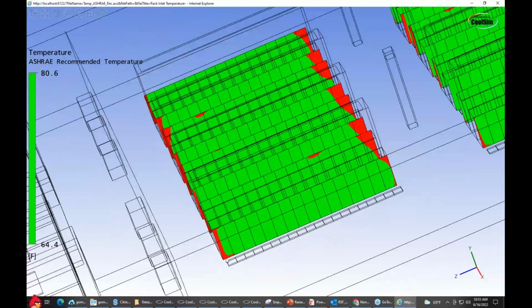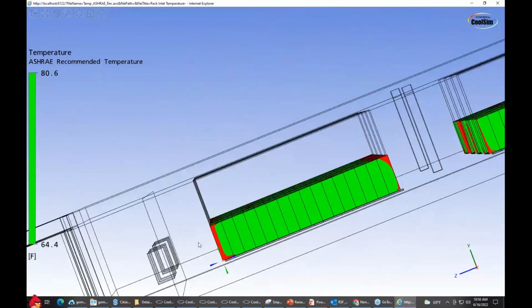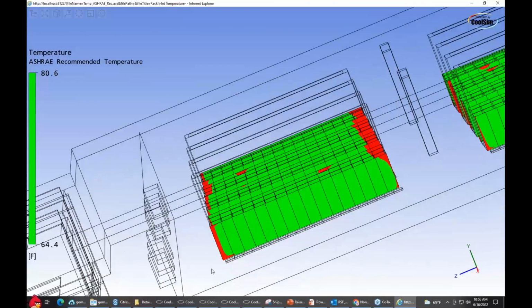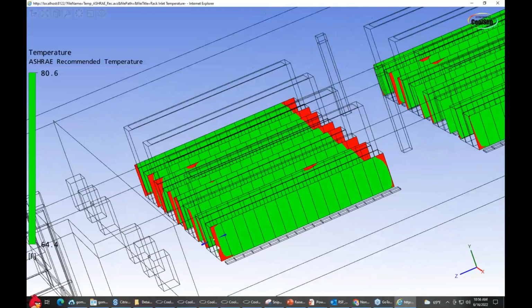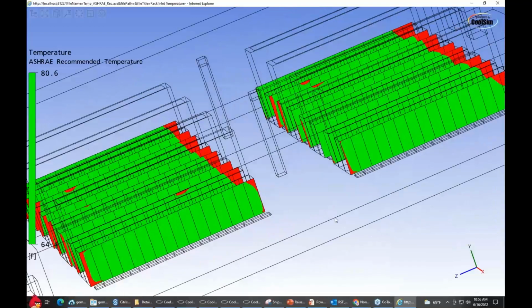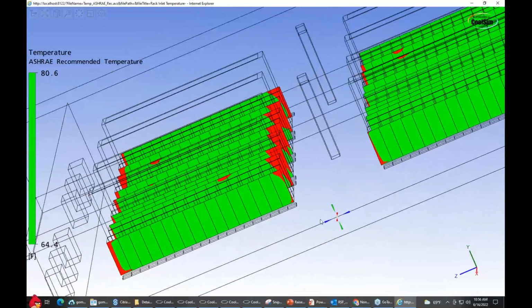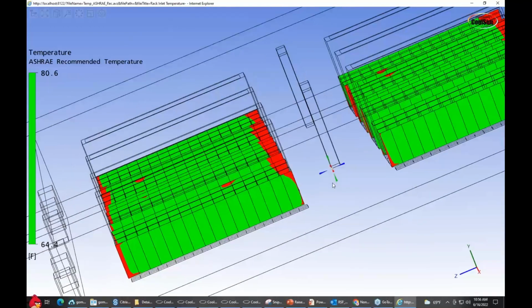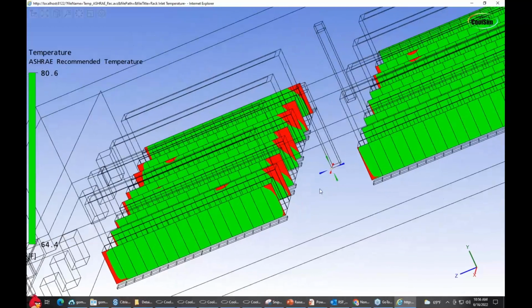There are tiles out there that are what we call performance tiles. They have fins underneath them that allow you to capture some of this air that's traveling by at high velocity. That's what's going on there. The air is going by at high velocity, and it's bending up, and so it's not getting to that edge. You can manage that with performance tiles. On this back edge, it's likely we have some velocity there too that's causing those to do the same thing.